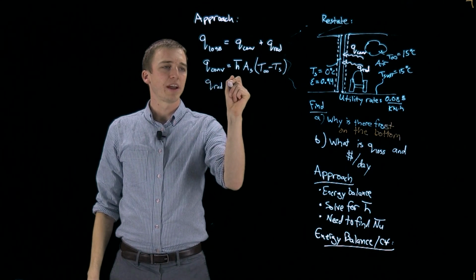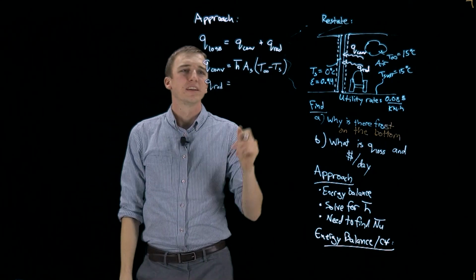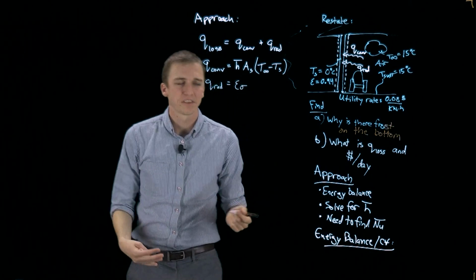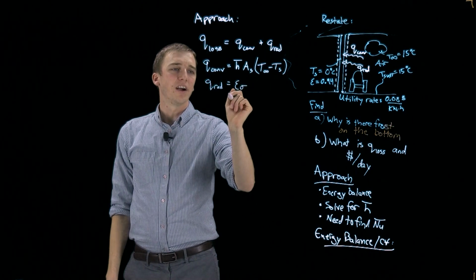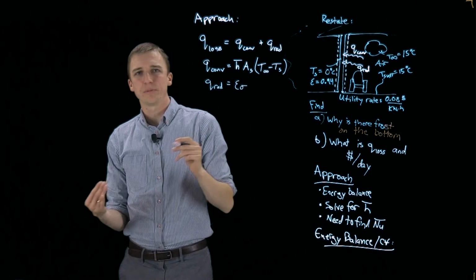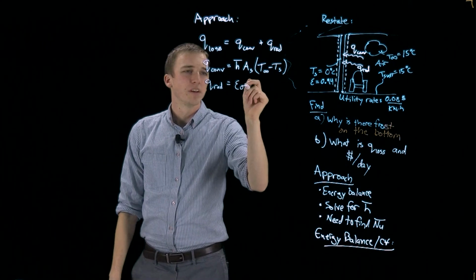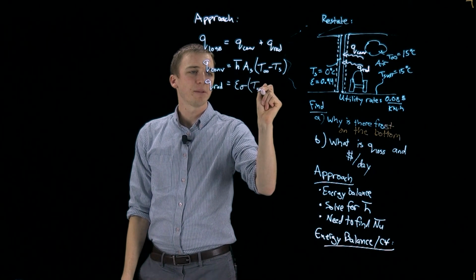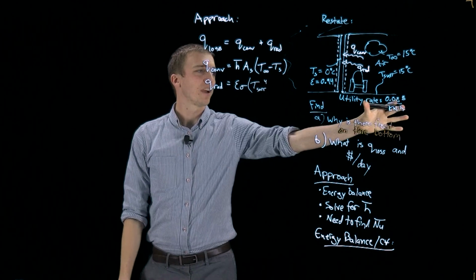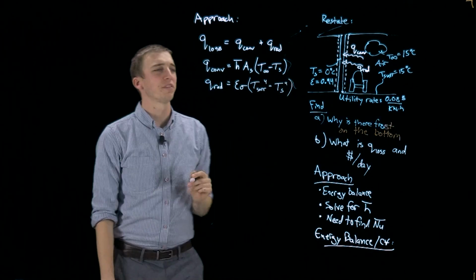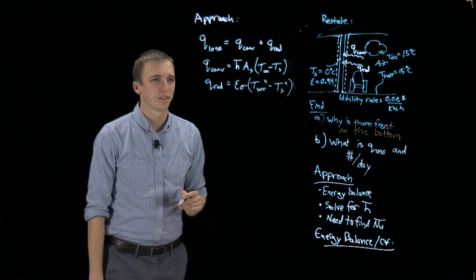Also, we're going to write Q rad, which is using what we kind of call the Stefan-Boltzmann Law, our emissivity of our window, which also would be the absorptivity of the window, multiplied by our Stefan-Boltzmann constant, times the temperature of the surrounding, the hot thing, subtracted from where the heat is going, the cold thing, Ts to the fourth.